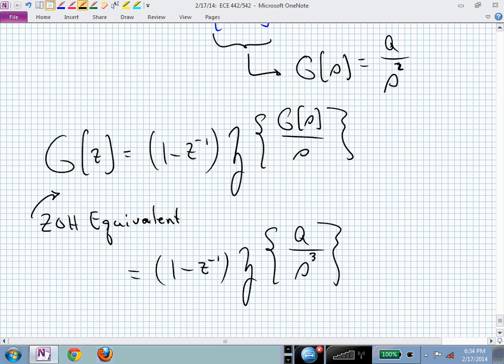Do you remember what happens when you inverse Laplace transform something over s cubed? What was 1 over s? Inverse Laplace transform of 1 over s, constant, right? It's 1. 1 over s squared, a ramp. 1 over s cubed, quadratic or parabolic. But we have to remember that this actually starts introducing some factorials in there.